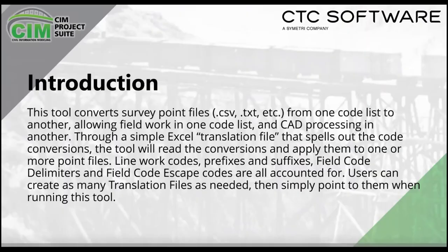Point File Converter is a survey point file tool that will convert all of our points from one code to another. So we can allow all of our field crews to be working in one code list, and then the CAD processing can be done in another if you need to. Through a simple Excel translation file, it will spell out the code conversions and the tool will read those conversions back and apply them to one or more point files.